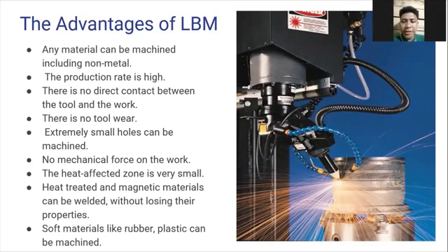Extremely small holes can be machined. There is no mechanical force on the work. The heat affected zone is very small, and heat treated parts can be welded without losing their properties. And the last is that soft materials like rubber and plastic can be machined.